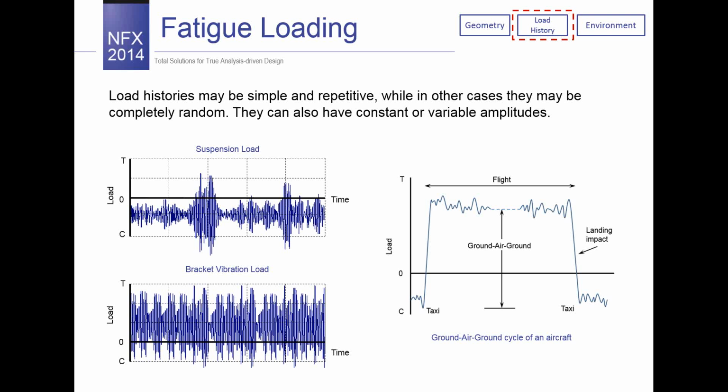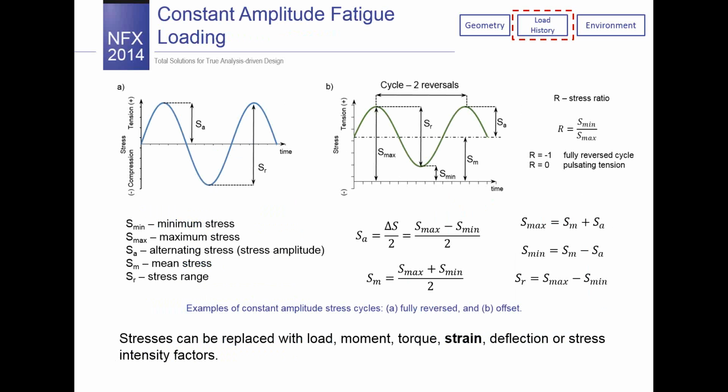And this means that it is also important to accurately measure the applied loads on an existing component or structure, and predict loads on a component or structure that doesn't yet exist. This is why we are doing this. And to measure the load history, we are using transducers, which are most commonly strain gauges, and they are attached to the critical areas of the component.